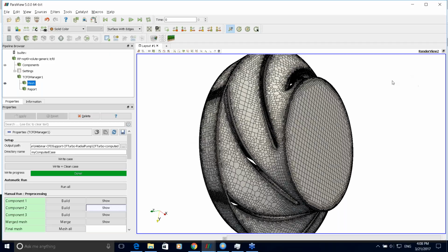And there was maybe one question regarding the hexadominant mesh. So hexadominant mesh, let's say the structured mesh with the hexahedras is the best for CFD, because CFD is based on finite volume methods, and finite volume methods really like hexahedras and everything perpendicular to each other. So hexadominant meshes are convenient for CFD simulation using finite volume methods.